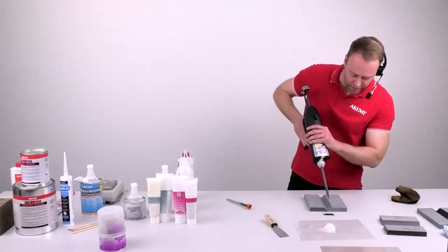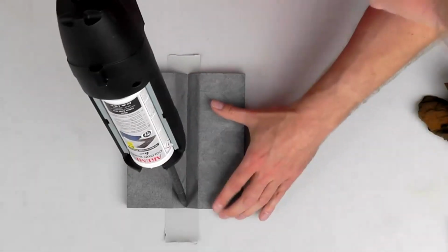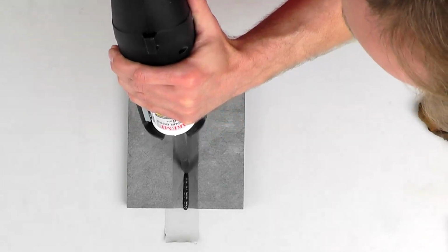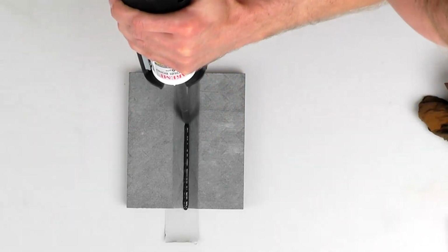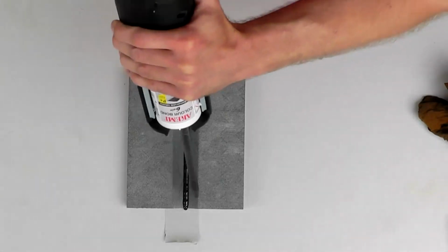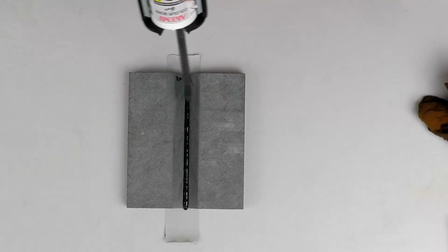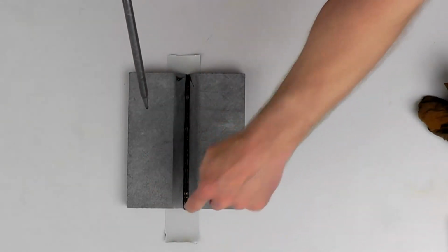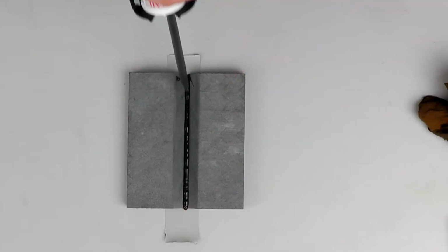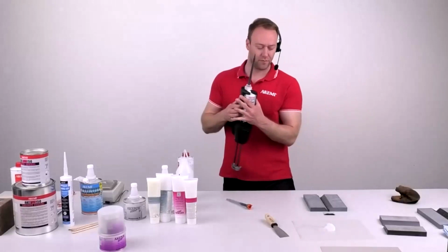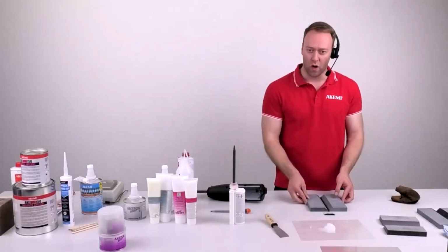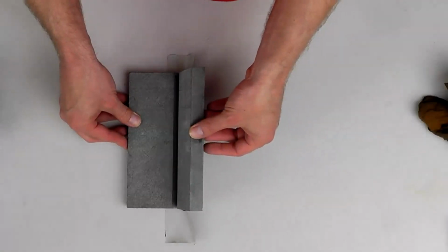And now we go on the top and place enough glue that it comes out of both sides into the miter. I don't move in a zigzag, because then when I press together, I already trap some air inside. So I start from the bottom and fill everything from the bottom, and now I press it together one time. I don't open it up again. So I press.